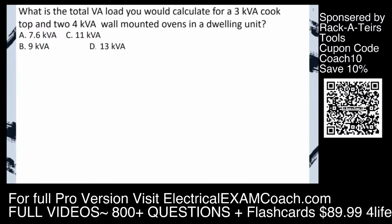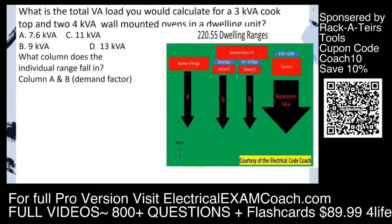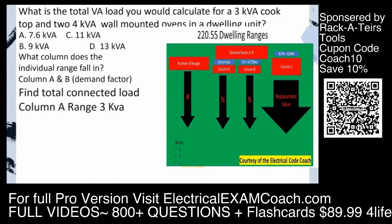What is the total VA load you would calculate for a 3 kVA cooktop and 2 4 kVA wall-mounted ovens in a dwelling unit? First thing we're going to ask is what column do the individual ranges fall in? Well, in this case, we find that it falls into column A and B. This question is very simple. All you have to do is treat the column A ranges individually, the column B ranges individually, and then total them together. So what we do is we find our total connected load. The column A ranges is just 1, so it's 3 kVA. The column B ranges, we have to do some math, and we end up with 8 kVA.